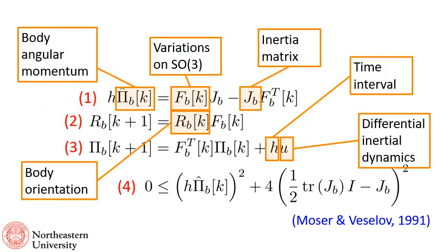The system dynamics and the equations of motion are described in a coordinate-free fashion. That means a dynamical system on the SO3 manifold without considering any local coordinate charts. The numerical integrator obtained from the discrete variational principle exhibits excellent geometric conservation properties, well shown in literature, and because of this, it is used here.